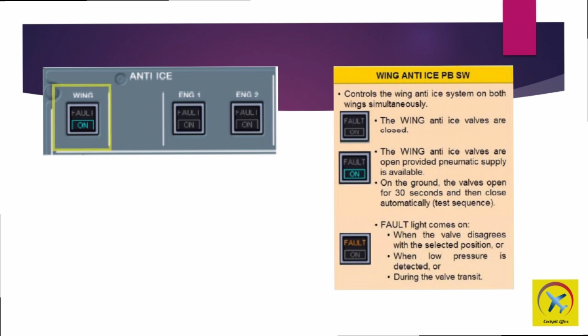And the amber FAULT light comes on when there is a valve disagreement with the selected position, or when low pressure is detected, or during the valve transit.